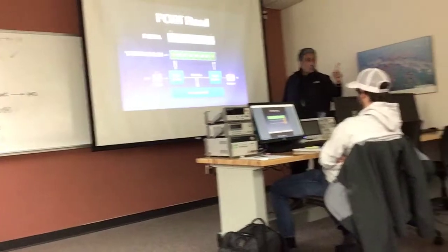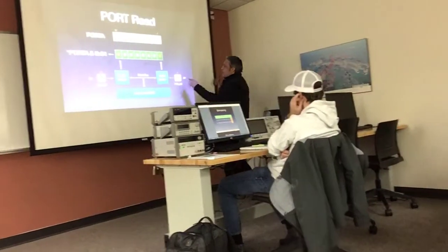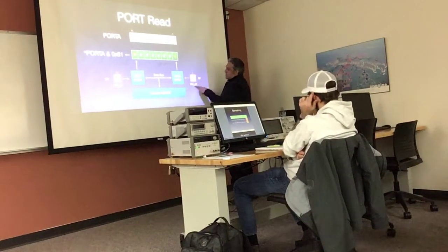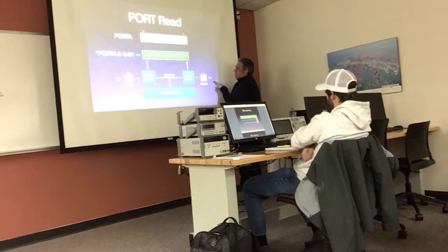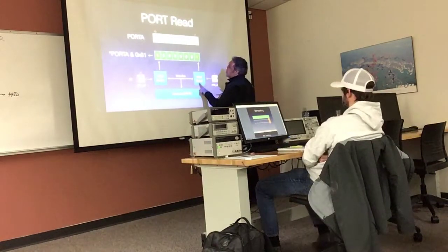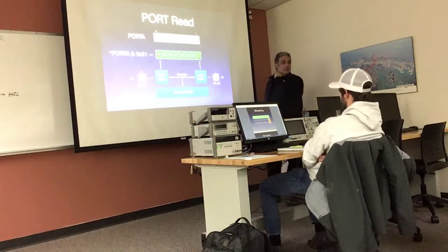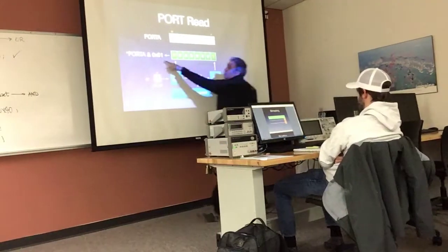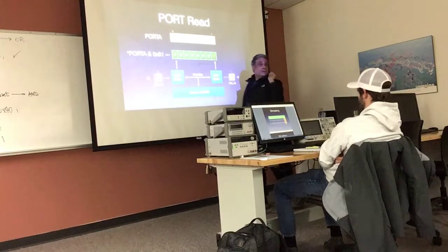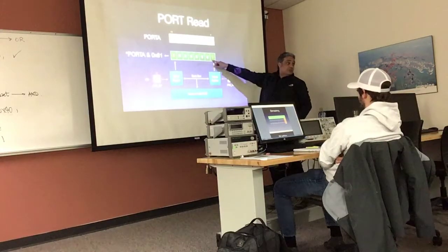The system will take care of the rest. If I put 5 volts on pin A2, the 5 volts will go through the buffer into port A, and the 5 volts will become a logical 1. So that when your port instruction gets hit, you actually see that logical 1.